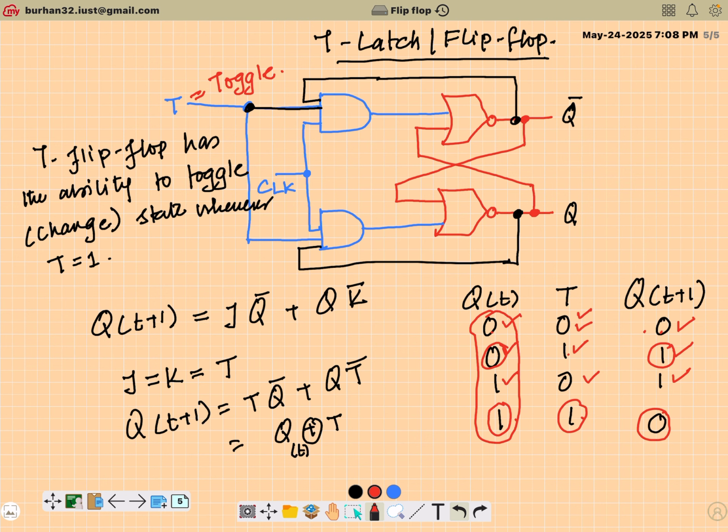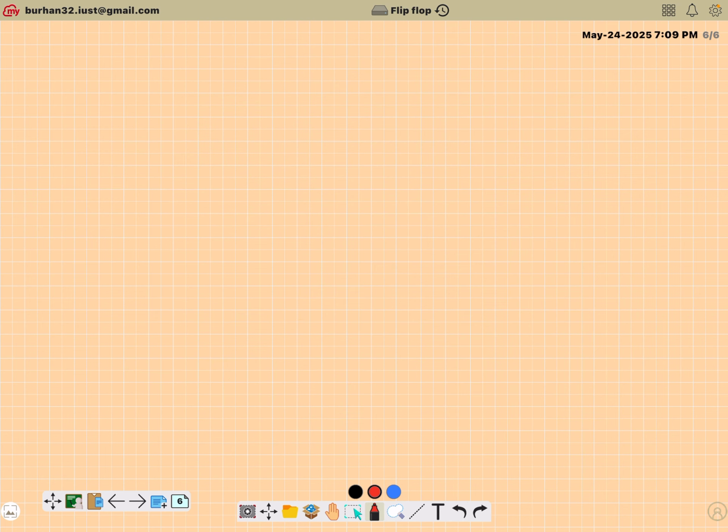And the next part, if you remember that in a sequential circuit, we have a combinational part, and we have the memory in the feedback element. Now, our first part of this sequential design was to discuss these circuits, come up with a circuit that can actually store my binary data. Fine. So we have done a lot of circuits which allow us to store bits. You see, the thing with memory is once you figure out how to store a bit, you can actually replicate the same thing to store multiple bits.